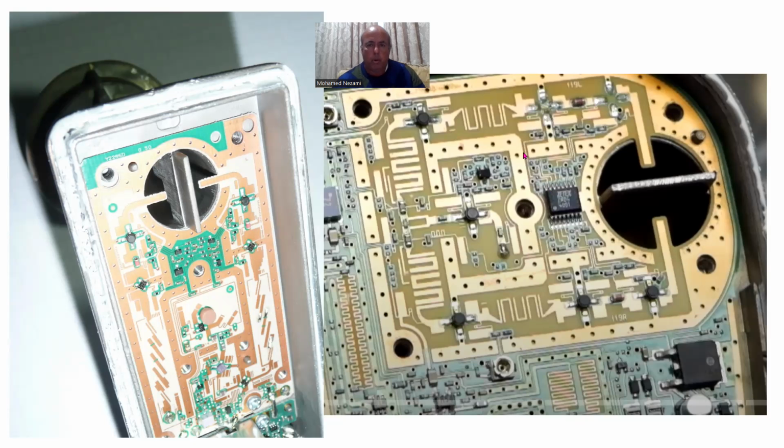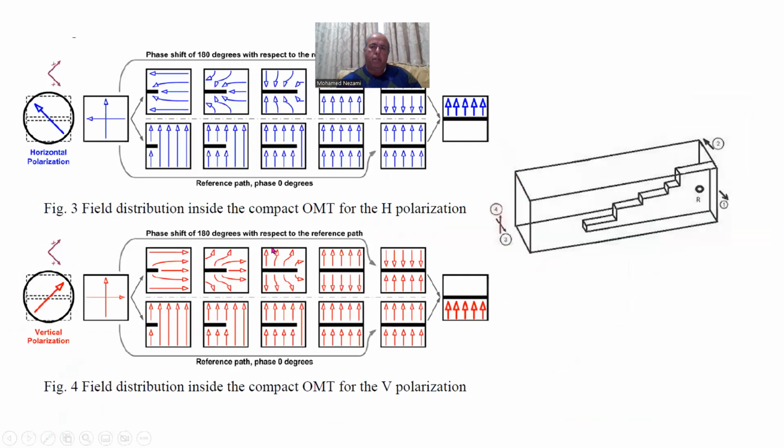Of course, you can see that these devices were removed. This is a junk board, but usually, like in this case, you get this polarization, be it vertical or horizontal. You get one amplification stage, another amplification stage, and then a hairpin filter, and then another amplification, then another filtering, and then you come in here to this Wilkinson combiner, okay, that goes into another amplification and then down to the next section, which mixes it with an LO and outputs an intermediate frequency. So there's your septum in here, which is nothing but this device here.